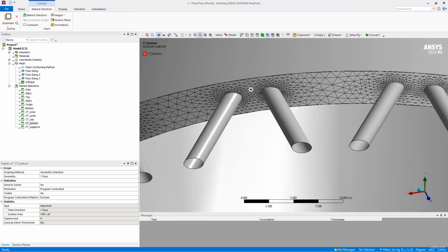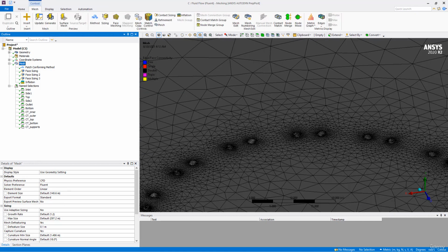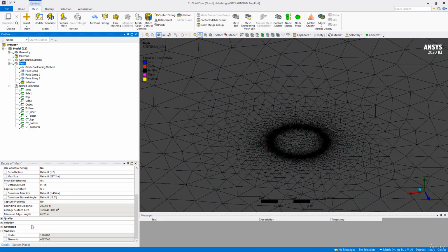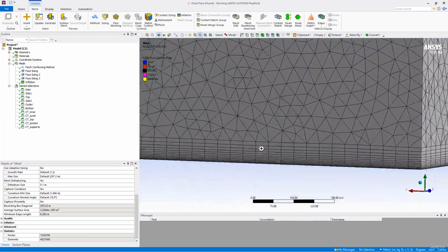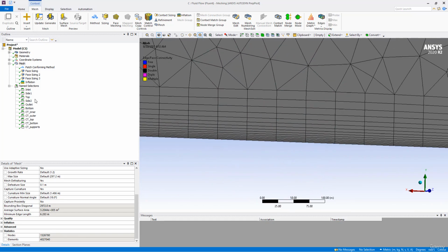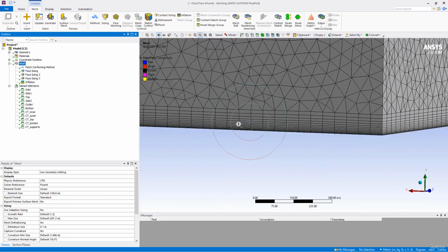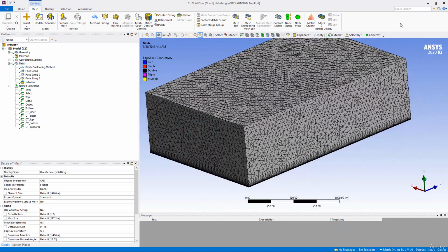And here is the mesh on the cooling tower bottom side, and the overall mesh size is equal to 4 million cells and 1.5 million nodes here. And you can see the number of prism layers from here is 15. Okay, so we are done with the meshing for the CFD part. So just close down this meshing application.